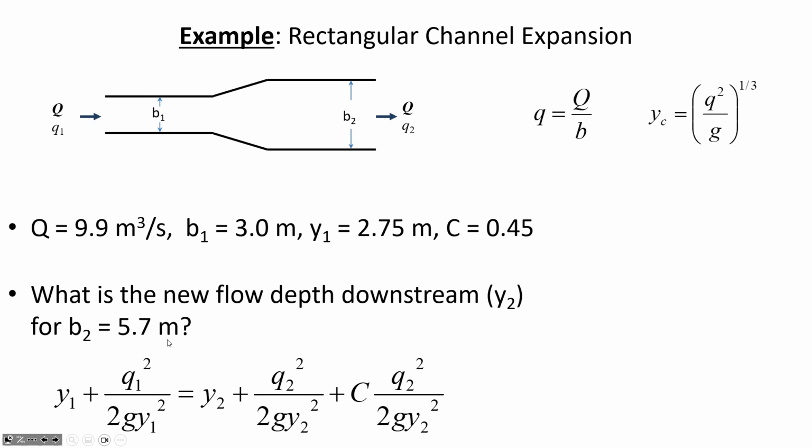So with this specific energy analysis, we're going to end up with an equation which is cubic. We're going to find the 3 roots, and to know which of the 2 positive roots to select, we're going to have to, in our earlier calculations, have determined what's the flow regime upstream. So is it supercritical, is it subcritical?